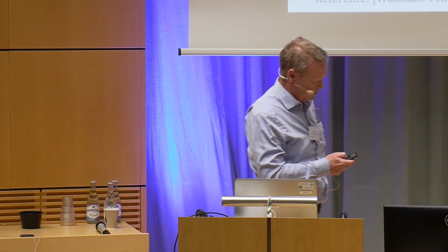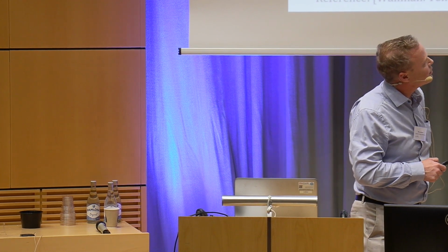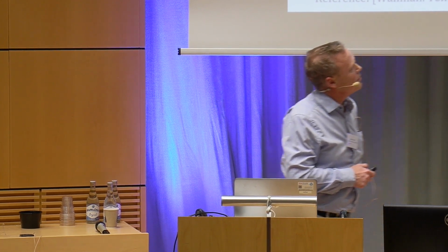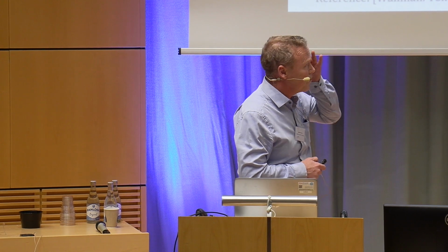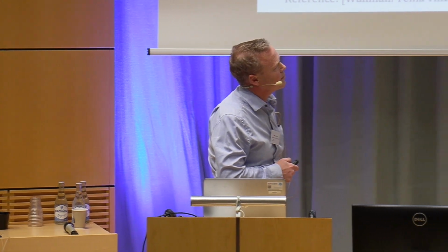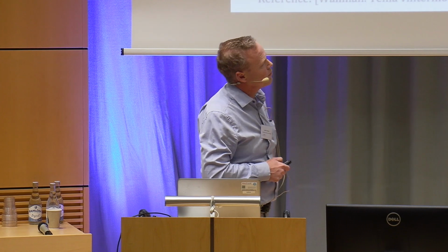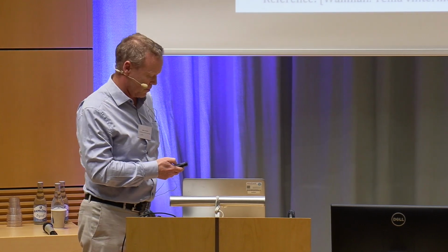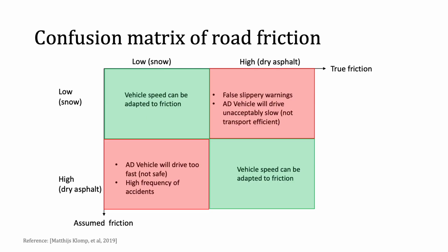So we're talking about low friction, mid friction, high friction. Normally for safe-driving vehicles, the friction should be more than 0.4, otherwise it's too slippery. So we're trying to capture the problems with friction.